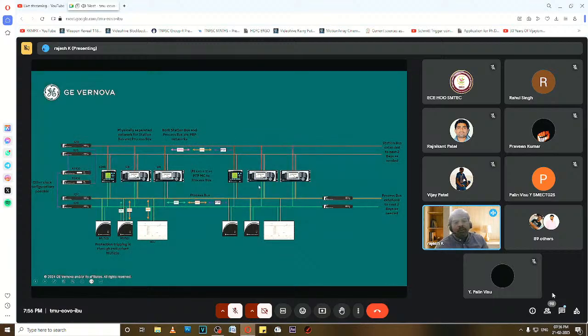So you have two buses: the process bus, which carries all the essential current and voltage parameters from the sensors, and the station bus for controlling. So it will be a full Ethernet-based substation where you have a highly accurate digitized substation. That's why we call this a digital substation. I hope you've got an idea how sensors like a Rogowski sensor, quasi-optical sensors, or CVT sensors are used in digital substations, and how they are implemented in the real world in a station where you have protection and control devices. So this is for the digital substation when it comes to the sensors for current and voltage.